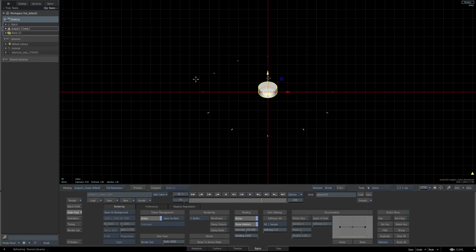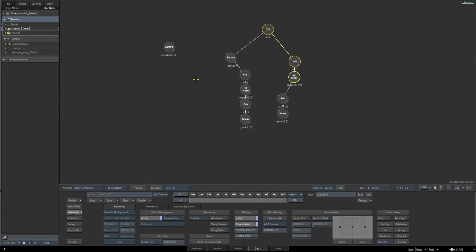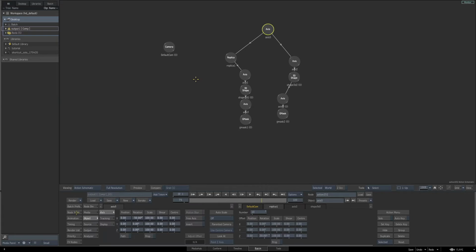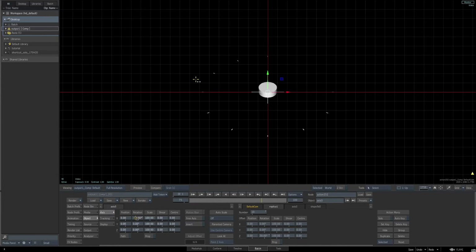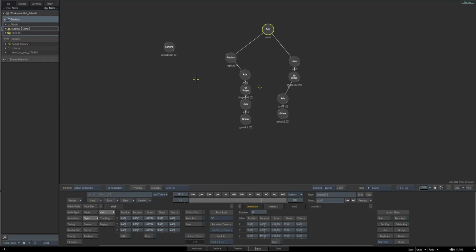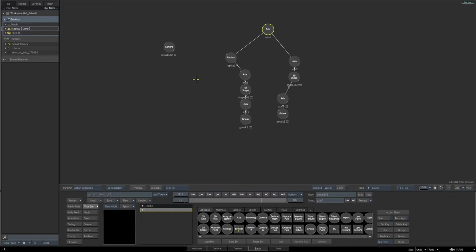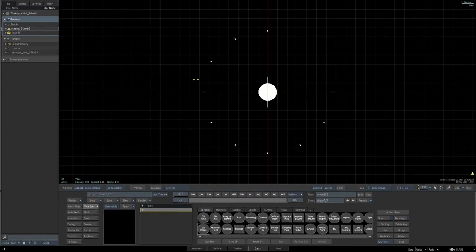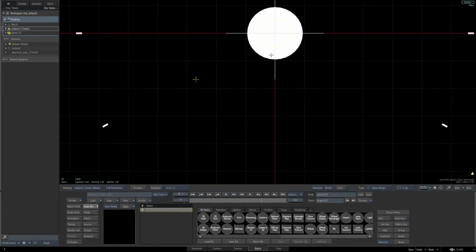Now we want to start creating the hands that will extend out of both sides of this round shape that we just created. Let's turn off our node preferences, and we want to select the top axis for everything. And let's reset our X rotation back to 0. So we're looking straight onto our objects once again. Back in our schematic view with the main axis selected, drag another 3D shape out into our schematic and it will be connected to the main axis. Go back to the result view and let's zoom in really close on our circle shape we created.